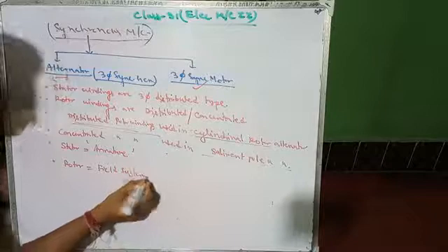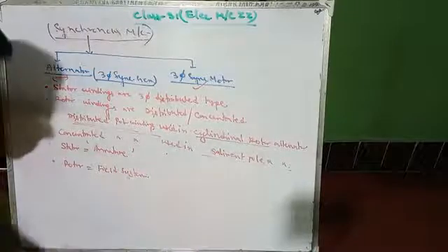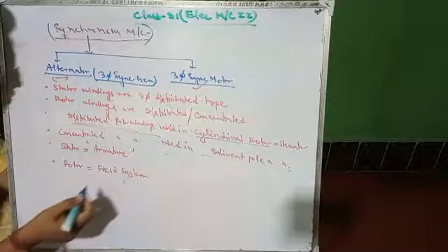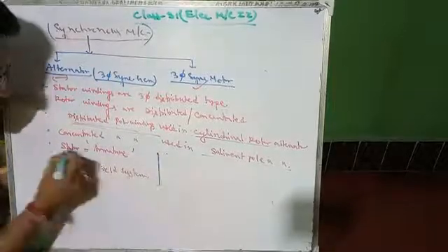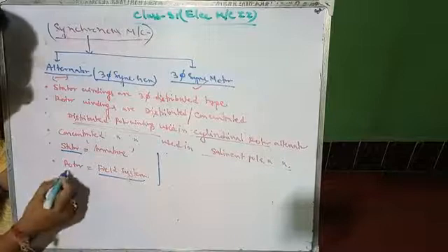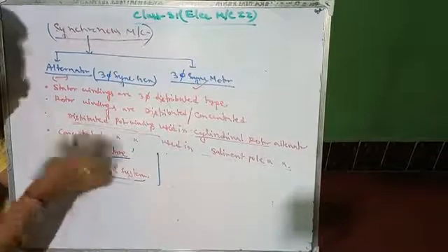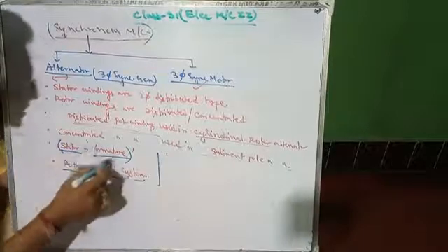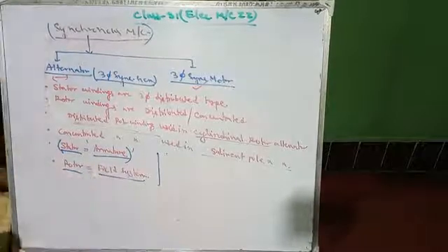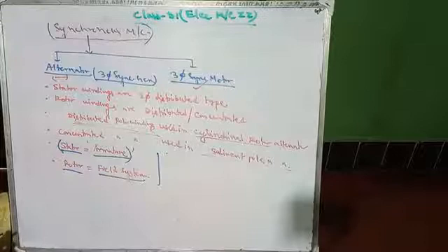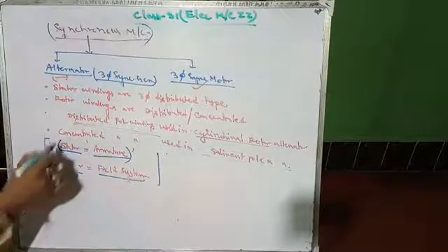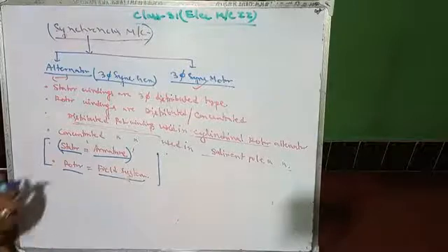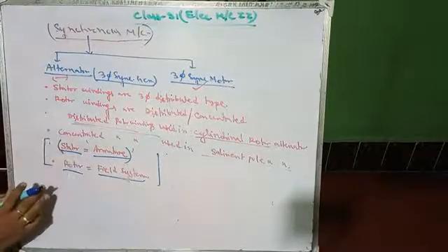This is the most important difference from the induction motor, where the stator is the field system and the rotor is the armature. But in the synchronous machine, the armature is installed in the stator and the field system is installed in the rotor. This uniqueness is in the construction of the synchronous machine.